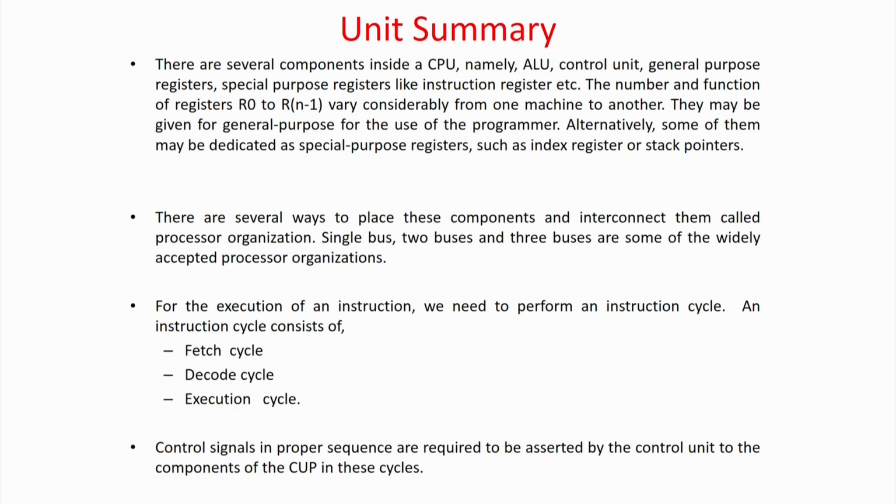Then we quickly jump to the different cycles of an instruction like fetch, decode and execute, and see the basic control signals required in each of these cycles. For some cases, part of the control signals are similar and part differ. Fetching an instruction will be the same for all instructions, because you have to fetch it from the memory, so the control signal sequence will be similar for any instruction in the fetch phase. Decode phase is nothing but taking the instruction from the memory data register to the instruction register and trying to find out what happens.